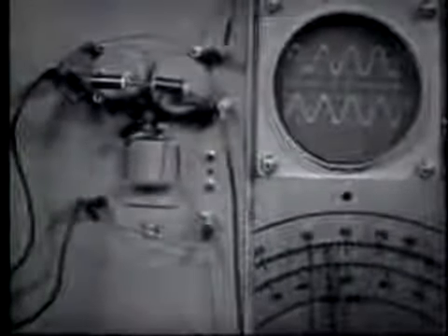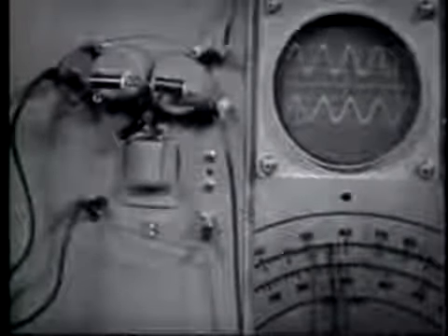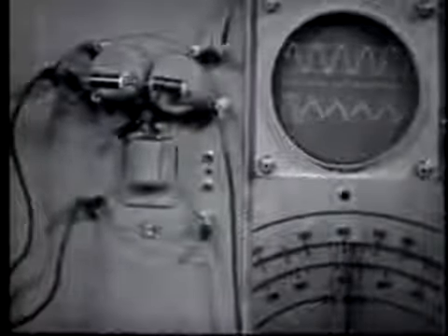So we have a T section band reject filter. Now let's check the frequency response of this circuit and see if we have indeed improved it. All right. Notice now that I only have to go down to about 550 hertz and I have maximum output from the filter. The same is true on the other side of the frequency we wish to reject. At about 650 hertz, I now have maximum output from the filter. So I'm now rejecting a band of frequencies much closer to 600 hertz. I have indeed improved the frequency response of the filter.